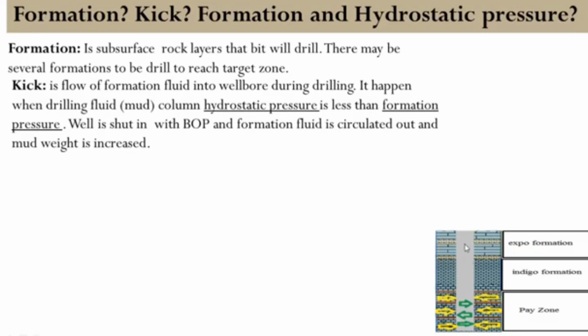This is the wellbore and it has the drilling mud or drilling fluid that must have a pressure greater than the formation pressure to sustain the pressure inside the rock. If the hydrostatic pressure of the wellbore decreases due to any reason, then the formation pressure, in this case the formation fluid, will start entering into the wellbore. This phenomenon is called kick.